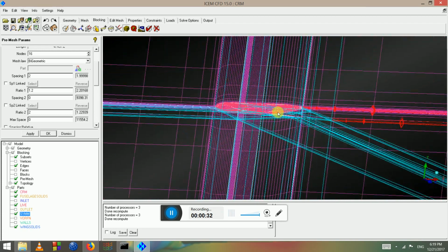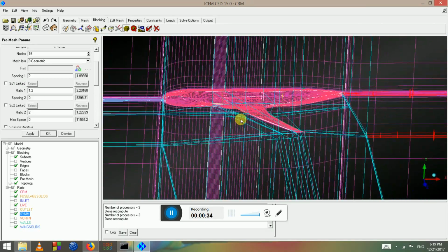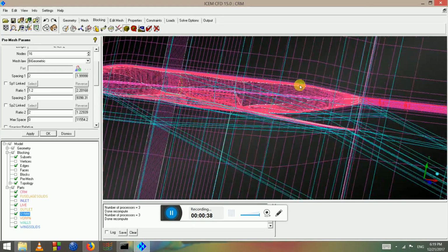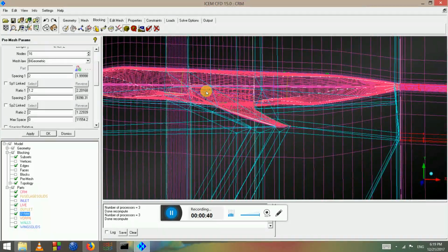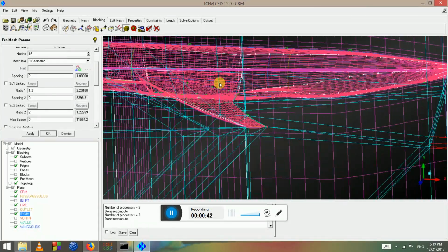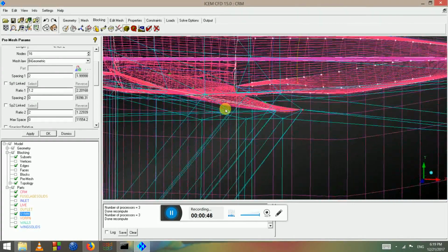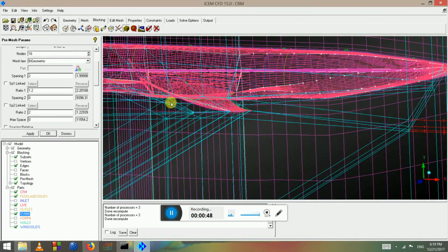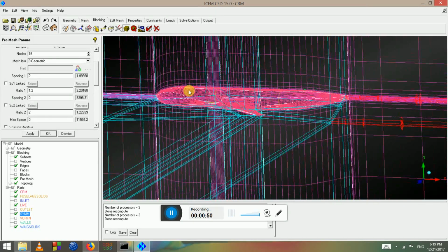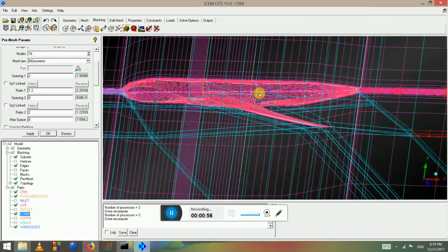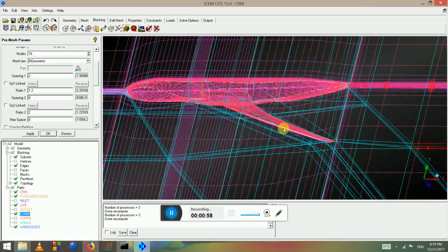We did the solid meshing and surface meshing, stopped halfway through, and then we improved the grid quite a lot. But today we are going to do the rest of the improvements, manually moving these edges to the right places and putting the boundary layer in an O grid, using the O grid capability of ICEM CFD.